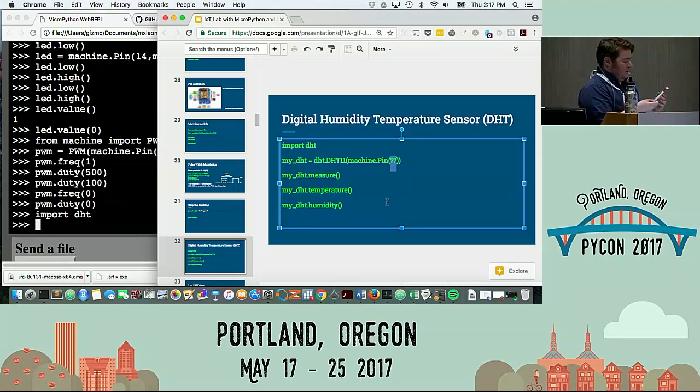If you take a look at the green wire on the left side of your board that's going into the DHT, look up and find what pin number, or pin name, on the board that you see. I see that it's connected into this pin, and I'm going to take that number and look at my sheet. I'm going to say, okay, that pin on the WeMOS means this GPIO pin. Don't shout it out. Give everybody a chance to look it up.